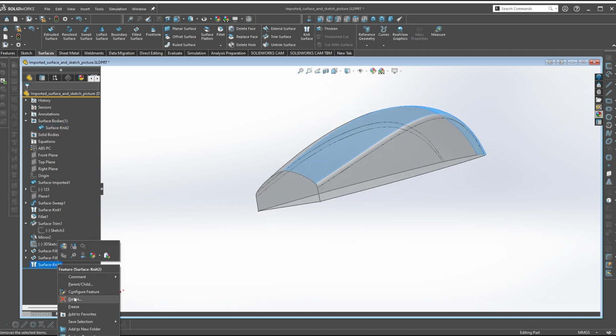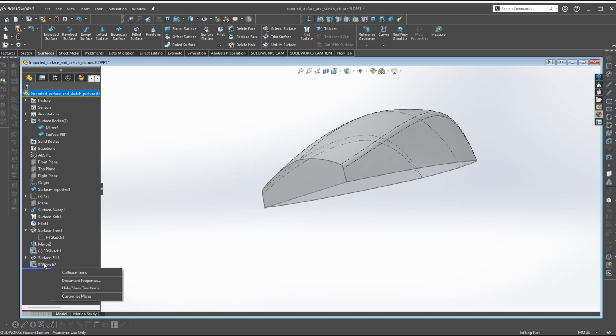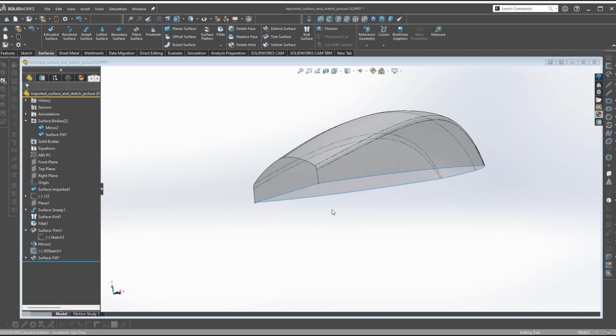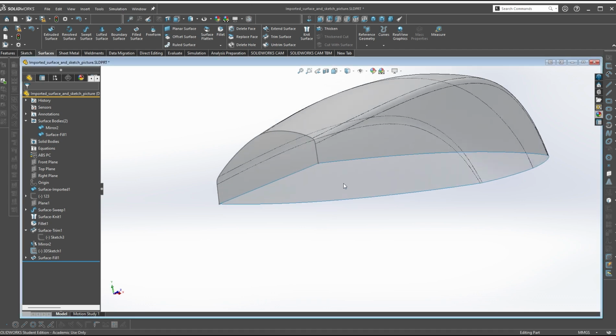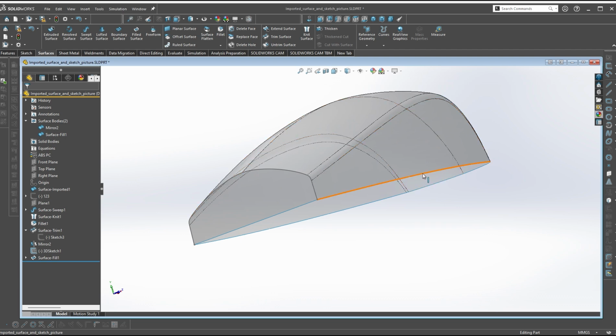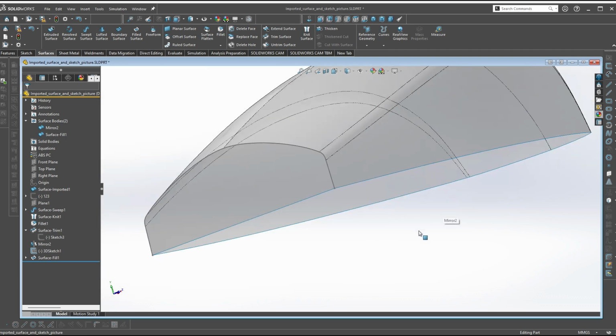So what we're going to do is walk this back a little bit, and this is maybe something that you're going to encounter on the actual test. So this is why I'm doing this. In this case, let's try just doing a filled surface without that spline, because something weird about this corner is different about how this did it. So let's do a fill.